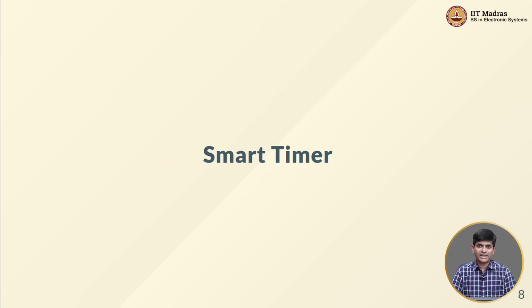Now we are going to look at a custom peripheral that we will create, and the idea is to take this up as an example and say, if you wanted to create a specific module of your own and you wanted to make it programmable in some way, what are the kinds of things that you would think about? What are the kind of parameters that need to be programmable, what are the kind of status flags that you might want to read back, and how would you implement all of these as part of a register bank?